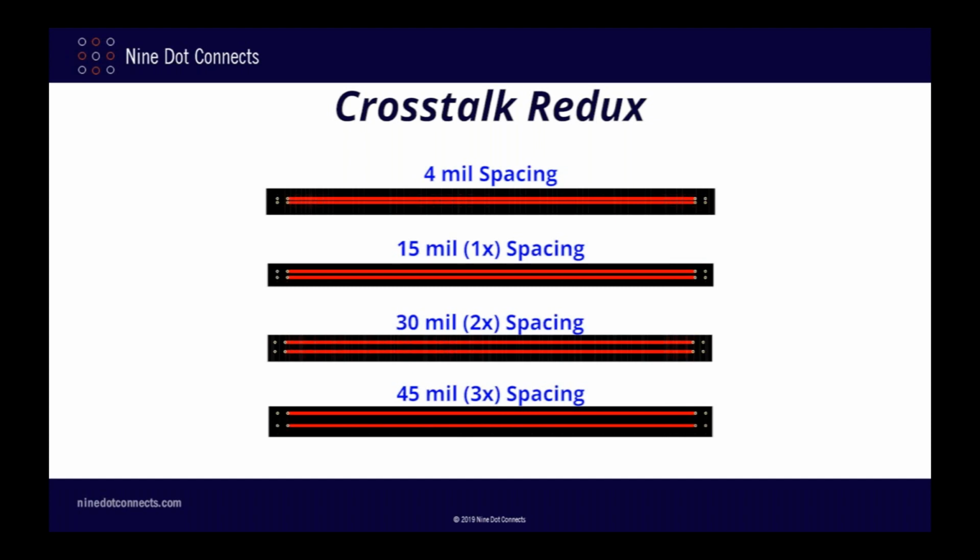Since spacing recommendations are usually given in terms of multiples of the trace width, I created 3 designs with 1x, 2x, and 3x spacings. The 4th design will have the closest possible spacing of about 4 mils. I'll then examine each of these designs in both the frequency domain and the time domain.